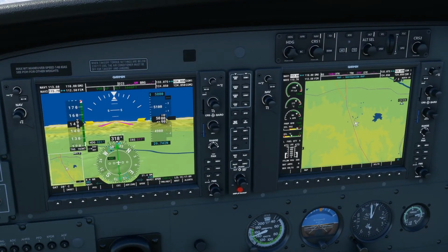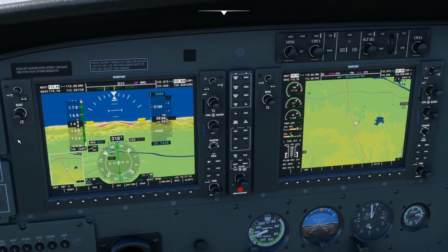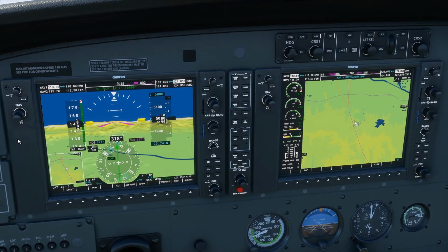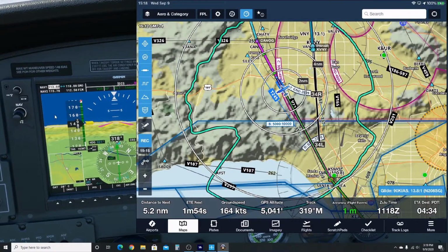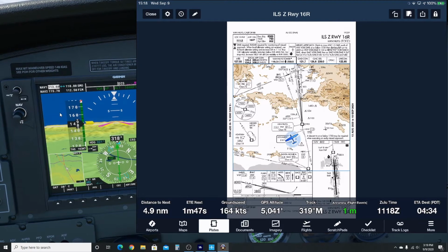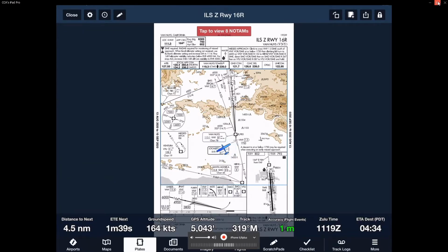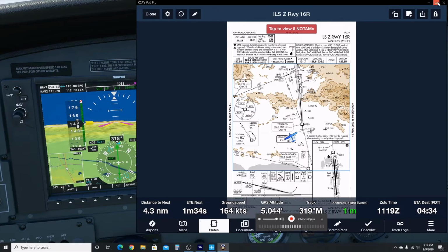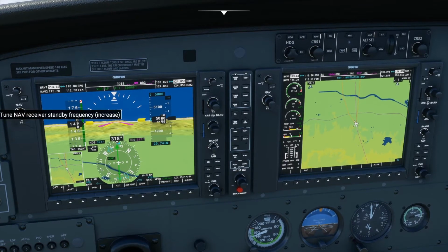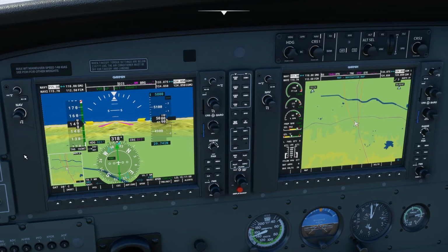So now we're using VOR 1. Next one will be VOR 2 from ForeFlight, and what we can do is start considering the ILS. So for the ILS, let's go to our chart here, ILS Zulu. Why is it looking so bad? I don't know why. 111.3, 164, okay. So 111.3 will be the next frequency. And the course for that will be 164.